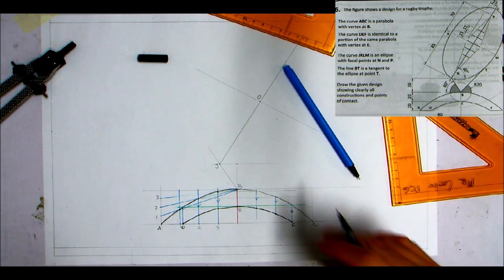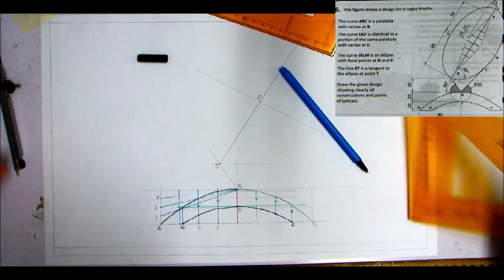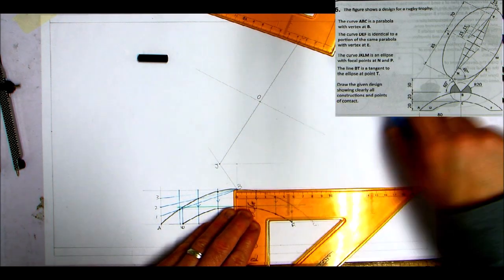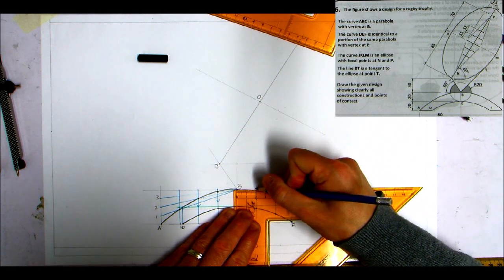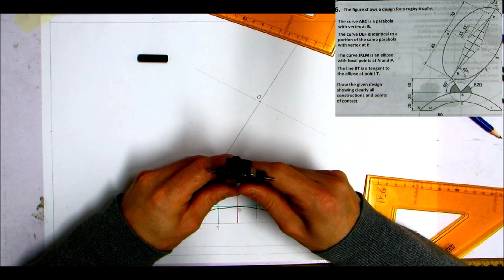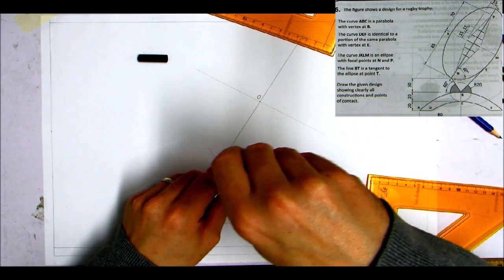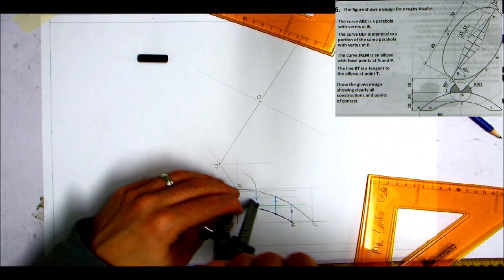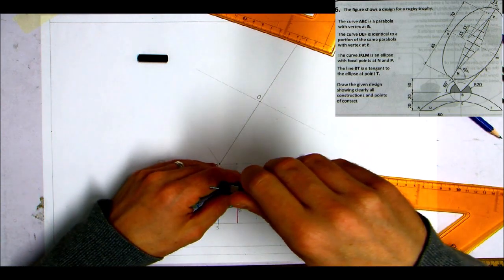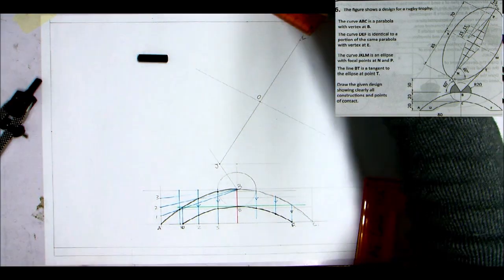Now we're going to move on then to the next section, and I'm going to do the circle next, which is of radius 20 millimeters. So again, on B here, I'll measure out 20 millimeters with my pencil, put a little mark, and that will set up my compass to draw my circle. Okay. And again, I'm going to draw it in light pencil first, and then I can go over it at the end to make it stand out. So that's that there.